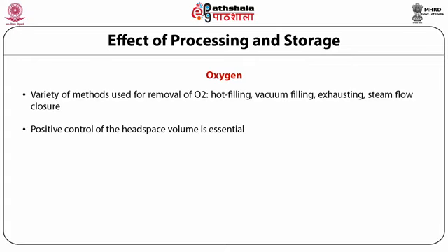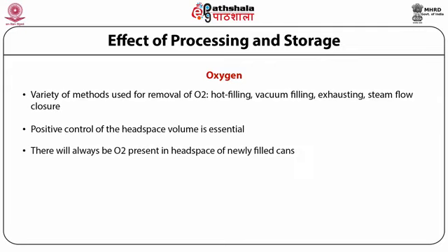Despite the above procedures, there will always be some oxygen present in the headspace of newly filled cans. The rate of oxygen consumption at this stage is quite rapid but decreases with time. The oxygen acts as a depolarizer, accelerating corrosion by reacting with the hydrogen formed in the can through a cathodic reaction.